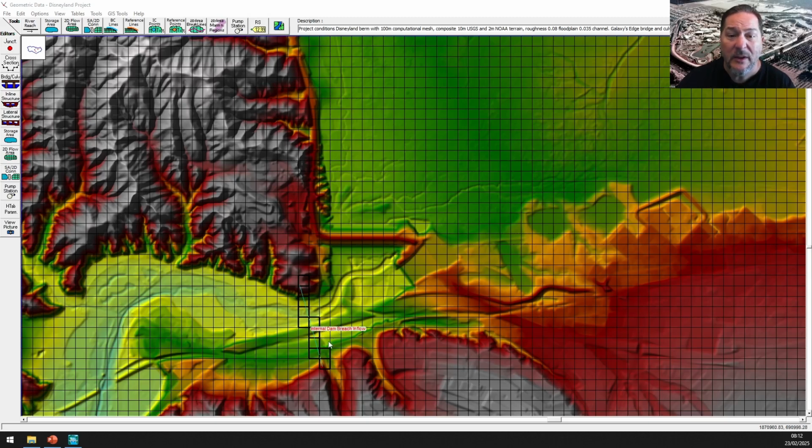Keep in mind there's no initial flow direction for flow that comes in here. So any inflow can just be bubbling up out of the ground. Depending on your flow rate, that could just be a trickle, or it could be this huge geyser just shooting out of the ground at each of these cells. So watch out. You can get some really funky results right around this area.